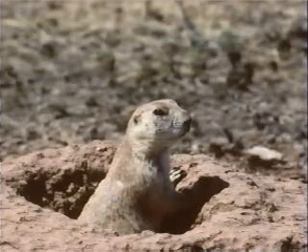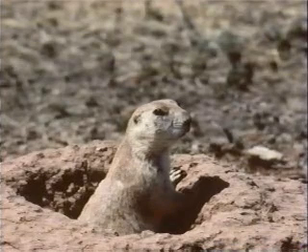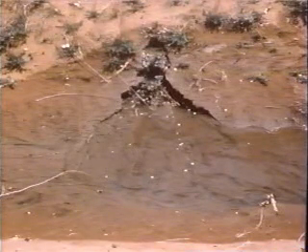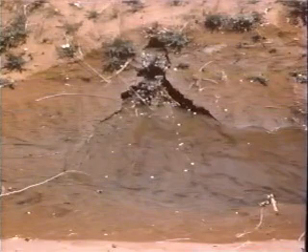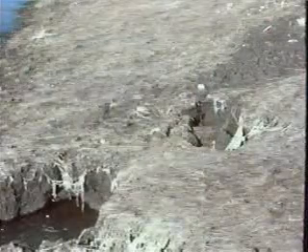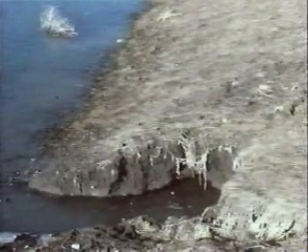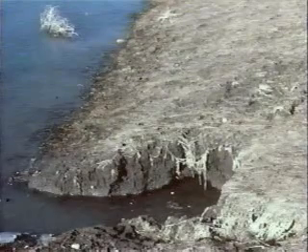Burrowing animals are frequently attracted to water and vegetation around embankment dams. Animal burrows can weaken the embankment and serve as pathways for seepage. This is especially true in small embankments with narrow cross-sections. Piping failures can occur when burrowing animals make passageways that connect the reservoir to the downstream slope. If burrowing animals are evident, take steps to have them removed before serious damage occurs.